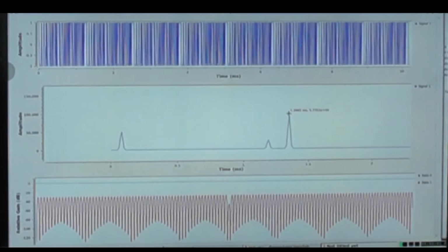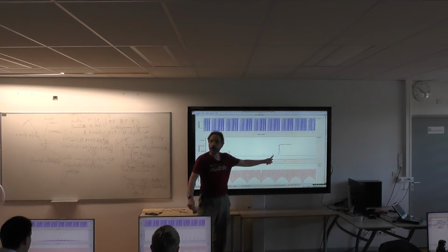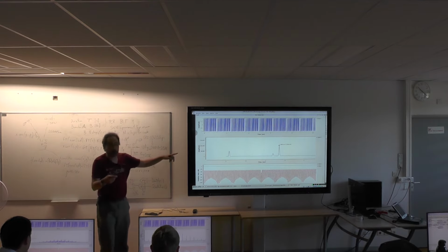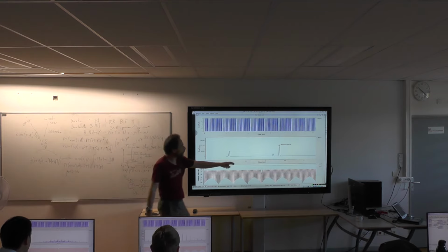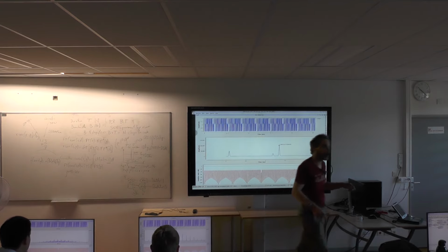And to answer the question about aliasing, this is where you see aliasing. It's because we calculate the correlation in the Fourier domain, and the windowing function is not perfectly canceling the side lobes. We have a bit of aliasing, and that's this leftover correlation. Okay?